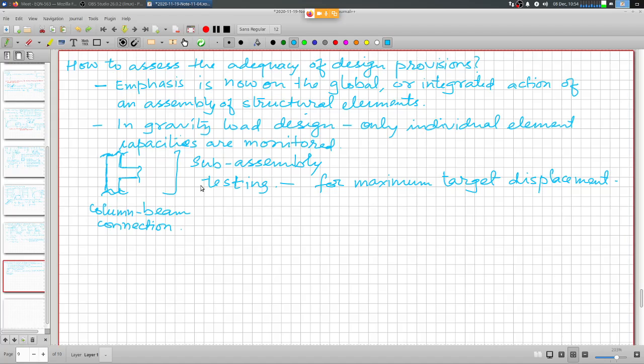And for that we have specific ductile detailing provisions that you can refer to in IS 13920, which prescribes certain reinforcement detailing, and of course the new version of IS 800 also prescribes suitable detailing for ductile steel frames, right?